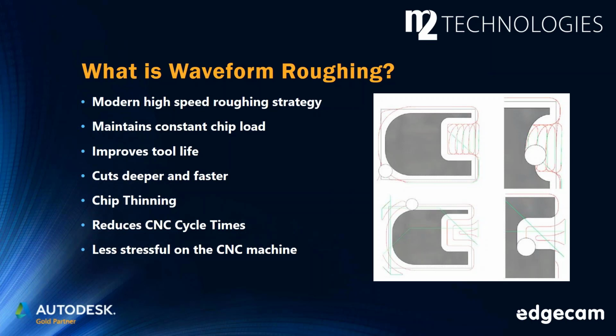If you look at the examples on the left, the top images show the high-speed roughing waveform tool path, and the lower examples show the more traditional geometric type shapes that have often been used in CAM software or perhaps on machine programming and other techniques. And while the lower images of the traditional stuff certainly have been used for a long time, they cause some machining challenges that techniques like waveform solve. So at the end of the day, what we're trying to do is have better tool performance, reduce the machining time, and be less stressful on the machine.